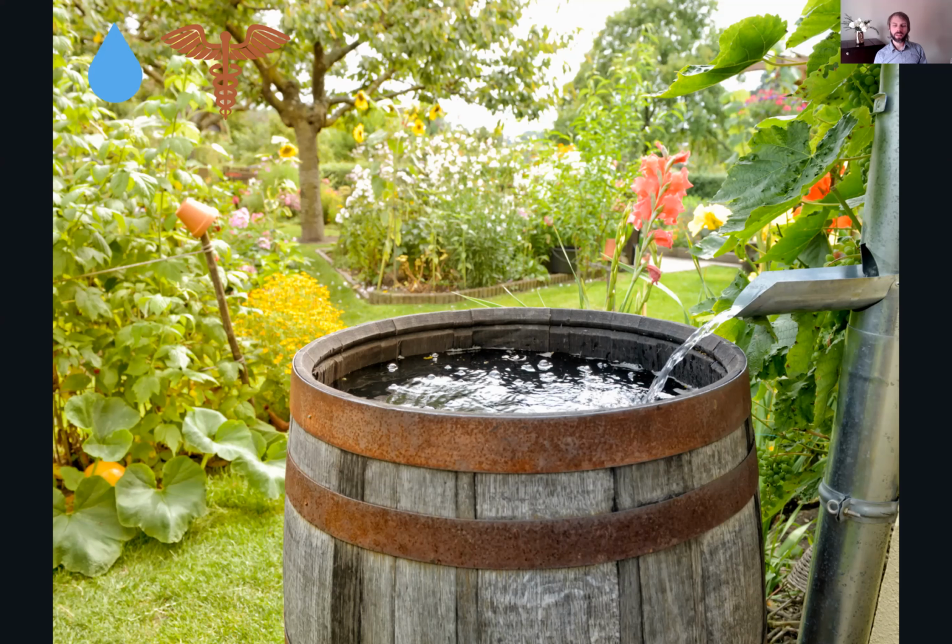And some of the things you need to know here is something called the 60th percentile or the 90th percentile or the 95th percentile. Enterprise Green Communities wants you to be at least at 60. LEED starts rewarding you at 90 and then 95. This is basically the amount of water that's going to come down during a huge rain event and overwhelm a system. This is a very novice overview of my limited understanding of how it works. I've got a link there to the EPA on a whole huge document on how to design a project and what you need to be looking for.